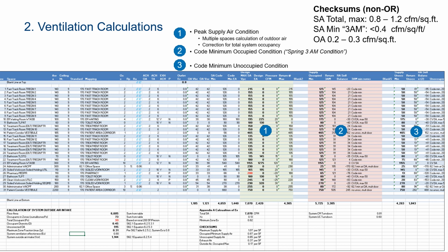Energy consumption in hospitals is almost entirely a function of the design minimum of your air handling system. So that means VAV has to be par for the course. In California, that has its own challenges. But we want to see that minimum occupied number down around 0.4 CFM per square foot or below, which corresponds, by the way, to an energy use of about 100 kBTU per square foot per year of HVAC energy.